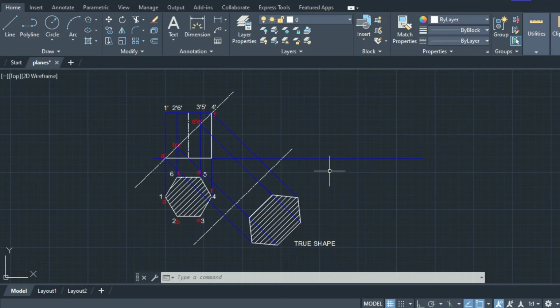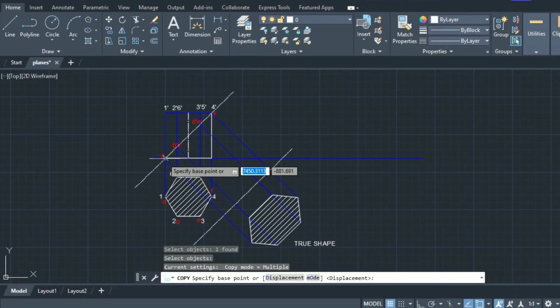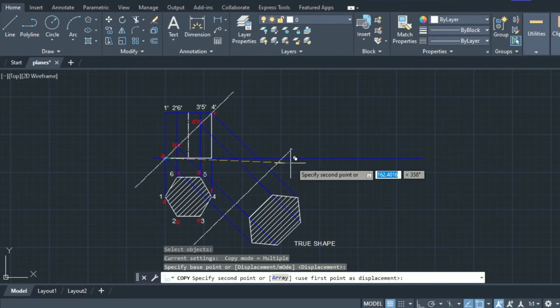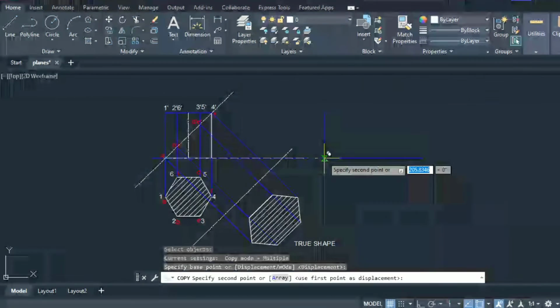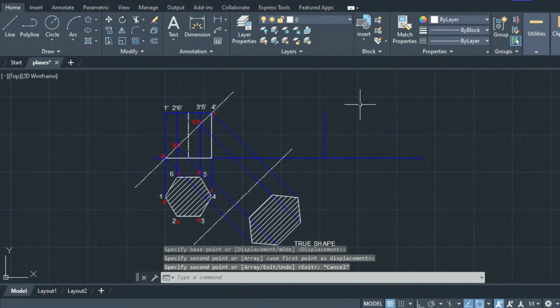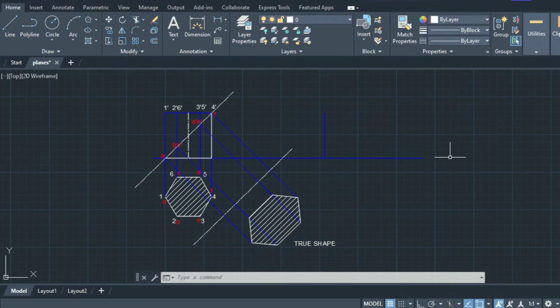Now we will see how the lateral surface can be developed. So this is what we are considering. This is a hollow surface, and once it is opened, all the cutting edges should be visible on that surface itself. Now to get the developed surface, we'll just copy this vertical edge of the prism from point 1, and at some random distance we'll place this line on the XY line itself. Now the height of the developed surface would be the same as that of what? The prism, but the length would be what?